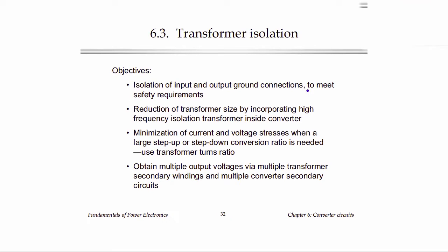Most of the time we're switching instead of conducting. So instead we could build a converter that includes a transformer that has a turns ratio and use the turns ratio to do most of the work of stepping down the voltage, and that converter then operates at a much higher duty cycle where the efficiency is better.